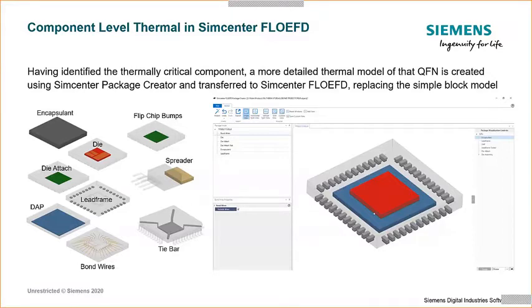The original block model, I suppose, is as much as you can expect from the data available from the PCB layout tool. And this will be a package outline and sometimes a height to create this lumped block representation. However, for both accurate thermal and accurate thermomechanical prediction, a more detailed definition of the internal 3D construction of the device is required. And Simcenter Package Creator is designed specifically for this purpose. It enables a parametric definition of the 3D package construction to be very quickly and easily created. And let's see how that plays.